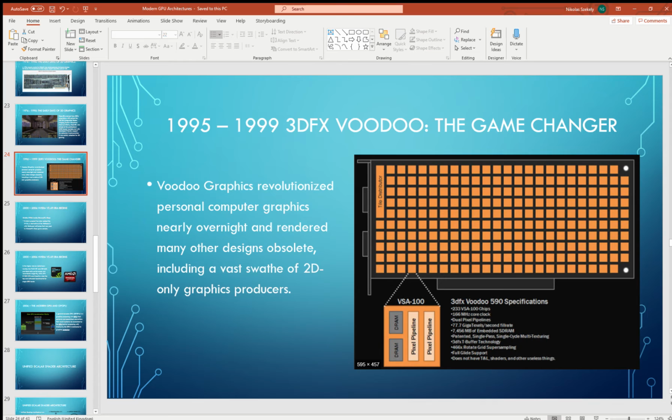in an attempt to offer a single card with 2D and 3D capability, but it didn't quite work out. Graphics cards back then had a separate 2D and a separate 3D card which were connected, and then that was connected to the monitor. 3dfx cut the right corners in the pipeline, reducing gate count without much impact on image quality. The Voodoo was easy to program and hard to slow down. The only thing 3dfx was missing was a complete 2D and 3D solution.